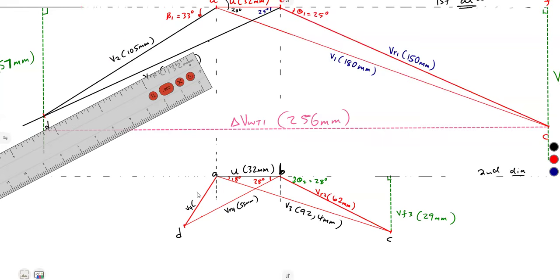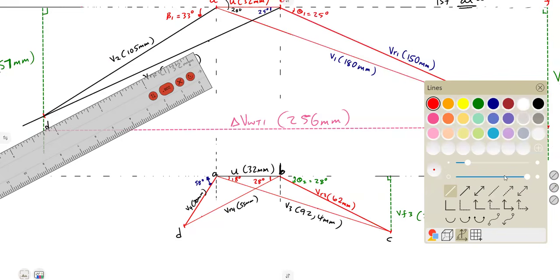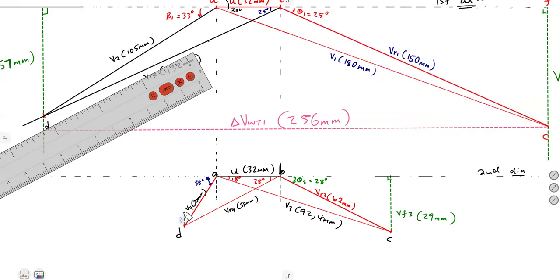We can as well measure that. It was going to be 3 centimeters, which is 30 millimeters, taken at the angle beta 2, this one, which we can measure approximately to 58 degrees. You measure properly, all right? And also your flow velocity at the end from D, the perpendicular.